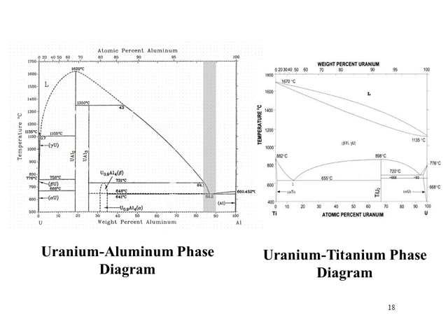If we mixed uranium with 25% aluminum by weight, it would fall right about here, and we would have a mixture of compounds based upon where it falls on this phase diagram. Over here, the 25 would be primarily the uranium-3 aluminum with a little bit of the uranium-2 aluminum.